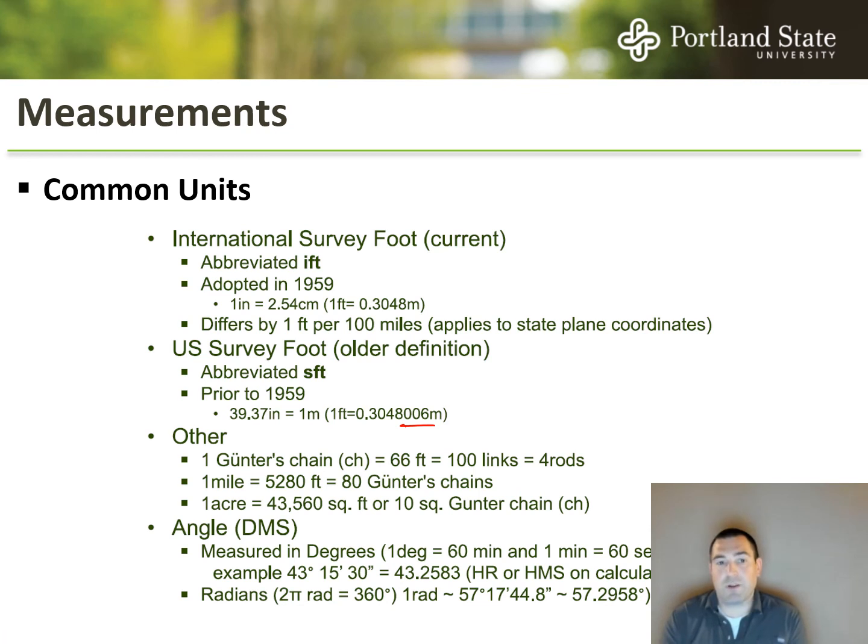Some systems will use international feet, IFT. Some will use US survey feet, which is either abbreviated SFT or just feet by itself.